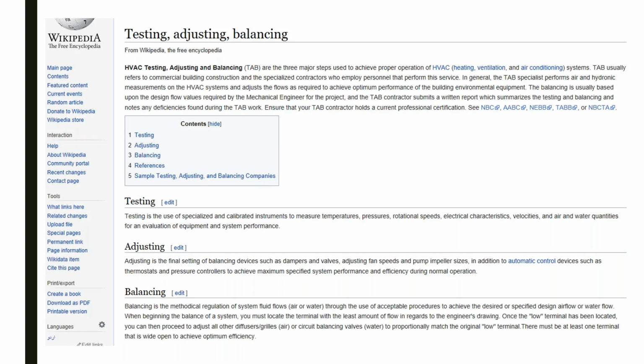You had no way of verification. We didn't go back with test and balance and say, yeah, we're doing what we're supposed to do. Because really that would be expensive. You'd have to go over the entire building. But they had some background to understand that we needed this many air changes per hour in this room in order for it to be more efficient. And that would reduce the total amount of air we were moving for the building, and that would reduce their energy use, but we didn't violate any safety laws or minimum ventilation or anything like that. So we followed the best practices up to a point, all the way to the point where we did not verify the actual airflow after the fact.